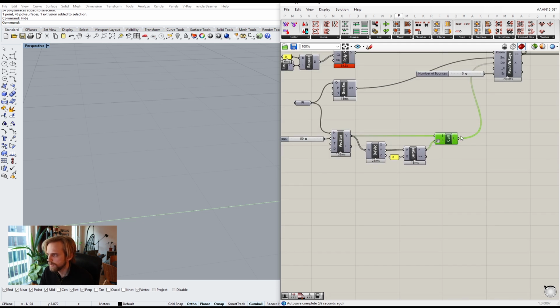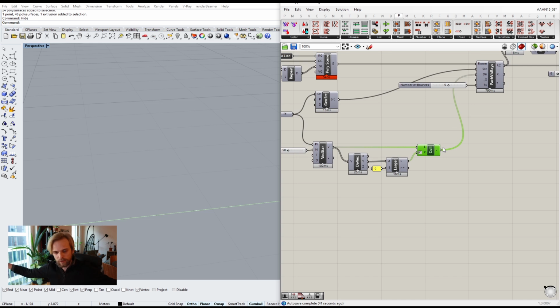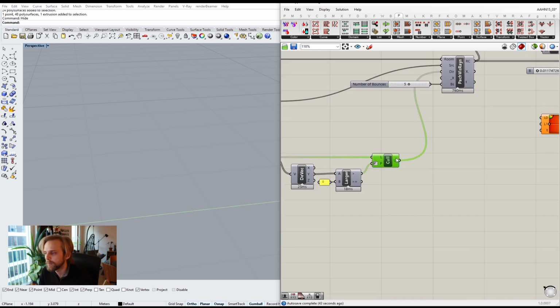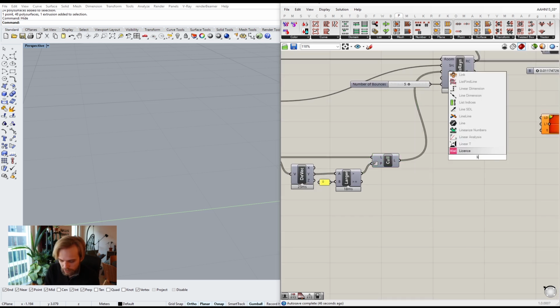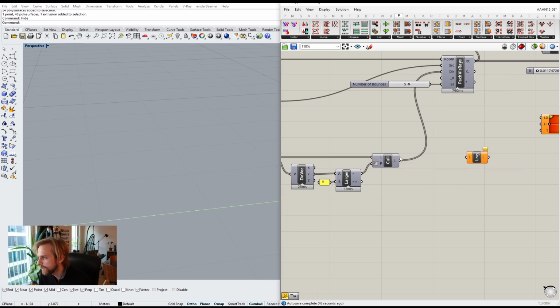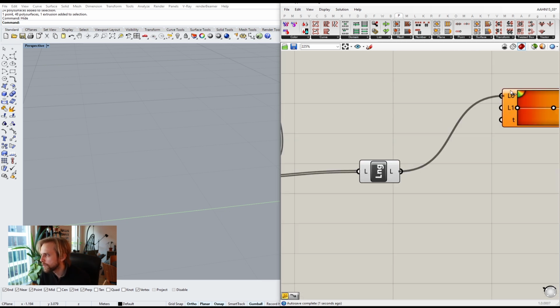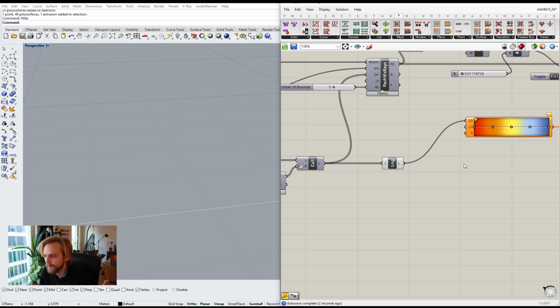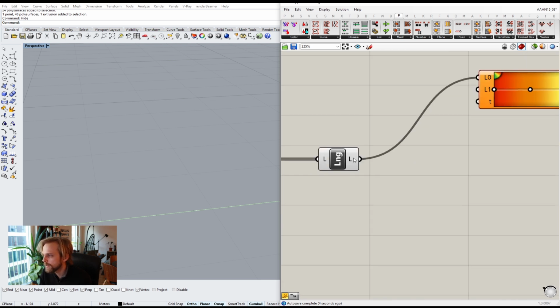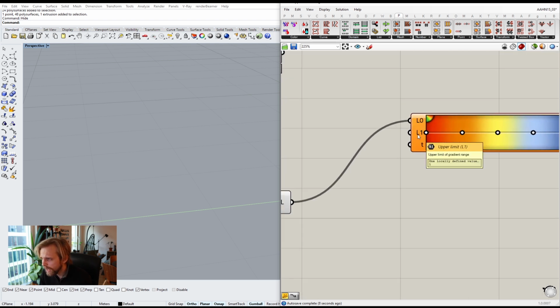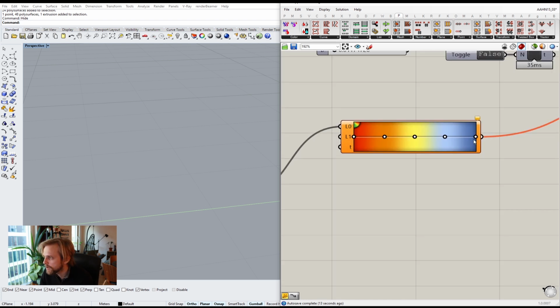These starting vectors from which the particles are going to be emitted is basically how many particles we have at the start. So I'll just measure list length of these vectors, and I'll plug that one into L0 like that, right? So red represents 7,804 in my case. L1 should represent 0 because it becomes blue when there's no particles left, right? So it gets cooled down.